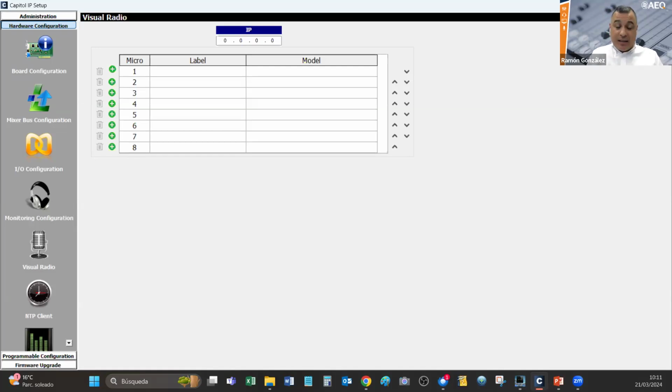For example, as I mentioned before, you can use the Dante option, Dante channels, in order to be integrated to an intercom system, for example, or you can use any input and any output, especially in the monitoring section, in order to provide a special communication through any of the programmable keys. So for example, you can do a salvo or an order functionality. You just push the button, and the operator could talk with other areas if you need it. It's very easy. It's not complicated.